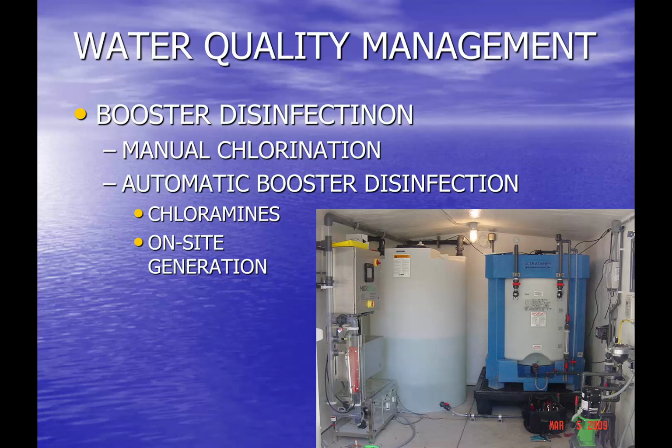So we would put salt in a tank, run water through it to create brine. That brine solution goes through the electrolytic cell, and that ultimately generates a relatively weak concentration of sodium hypochlorite. But for reservoir disinfection residual management, you don't need a high strength. With the on-site generation, we were getting somewhere in the 0.6 to 0.8% sodium hypochlorite, so far less than the commercially available 5.25 or 12.5% solutions. But again, when you're just talking about trying to maintain a chlorine residual in a reservoir, that's sufficient.